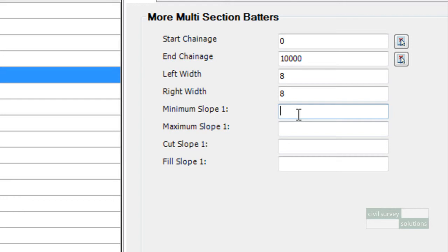So as mentioned, if the slope to this width to the surface is outside the range that I specify, then the maximum slope is used and the second leg is formed. I'm going to set this slope range at -8 for the minimum and 4 for the maximum.